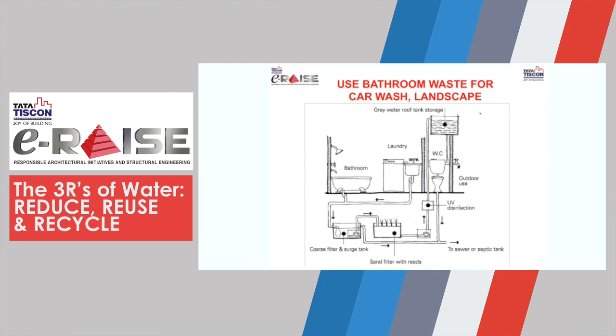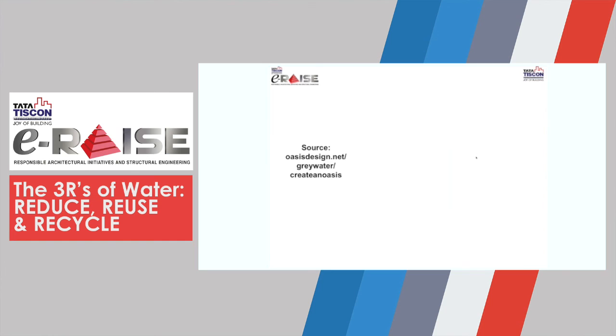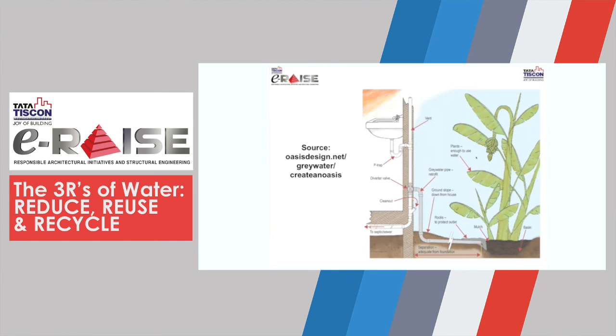Use of bathroom waste for car wash and landscape. Yes, this is another graphic that shows how this can be done with simple treatment. There is another better graphic which I will show you soon. But here is a very simple system by which the water from the hand wash, after the trap, is coming down the pipe and being diverted. Here is a valve that diverts the water onto the exterior of the building, so that it can be taken to a plant. So you have mulch, the water is coming from here, and it is a direct system going from basin to landscape. And of course, if there is too much water, or if there is any need to send it to the sewer, then the diverter valve doesn't work. It can also go to the septic or the sewer system of the particular area in concern.